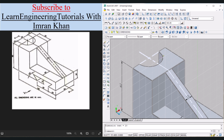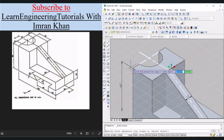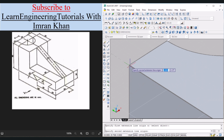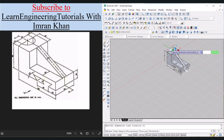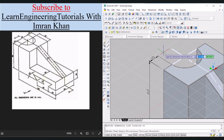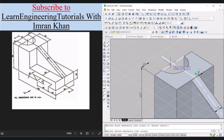Now we have to add dimensions over to this surface. Click on face UCS, click on this face, click on accept, click on linear, click on this endpoint, then this endpoint. Move the cursor away, click. Press enter to activate the same linear dimension command. Click on this endpoint, click on this endpoint, move the cursor in this direction and click.